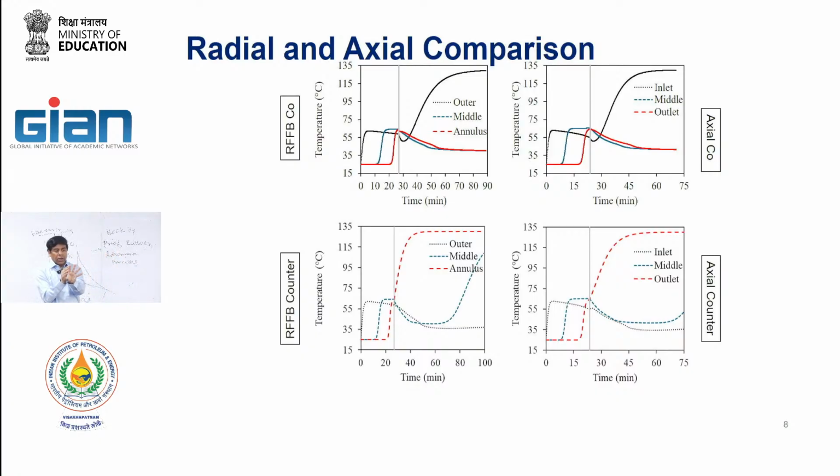You cannot change the direction in Aspen, like in AdSim. Basically you cannot say that I have co-current at this time and the other side moves from the other direction. That is not possible. So you have to write a script that ACM will solve. This is still ACM, it will still solve it, but their AdSim model itself is not set up for doing that. Aspen doesn't consider velocity as a vector. It just considers it as a scalar.